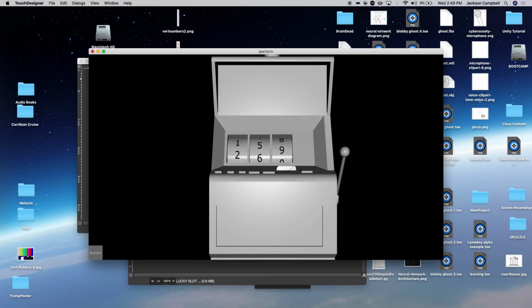What I think you could probably accomplish this week is to figure out how to move this button to be over the handle and how to make it invisible. All you have to do is go in there and turn alphas down to 0 and get rid of the text. There are some parameters in there called border. You can turn on those borders temporarily so you can see where the button is and position it where you need it. So you could do that. The other thing, that will probably be in the video anyway.